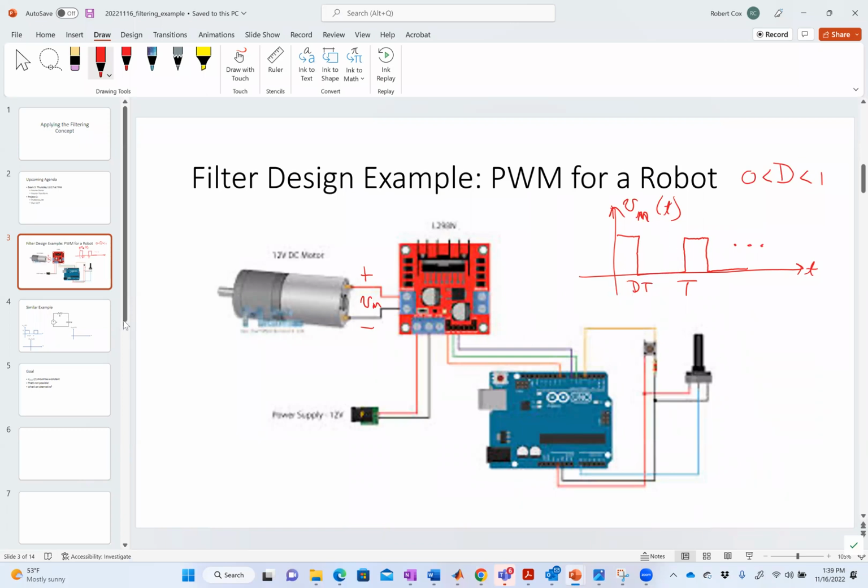So if I change this D value, I could think of it like that. Now, what that means is that this motor has a voltage input and a speed output. The way I talked about speed was a capital Greek omega, right? This guy has a transfer function, omega. And so this is going to cook your noodle later. Omega of omega.